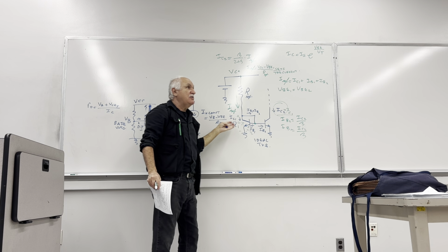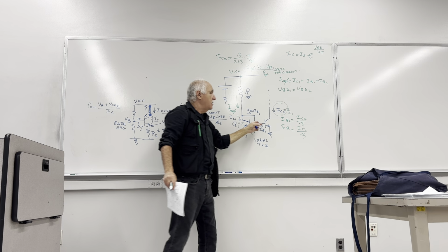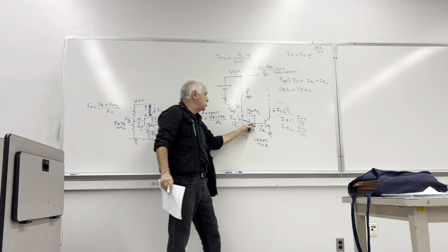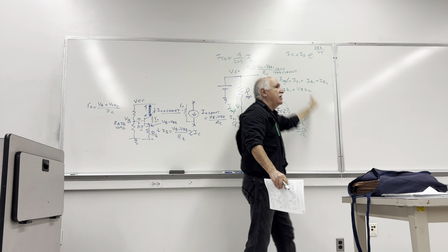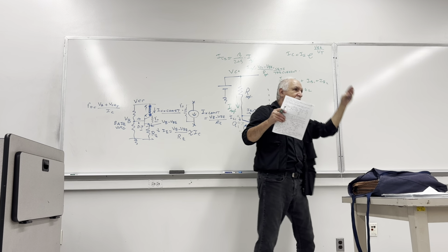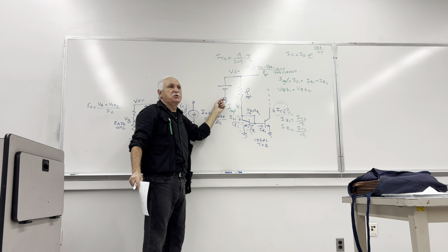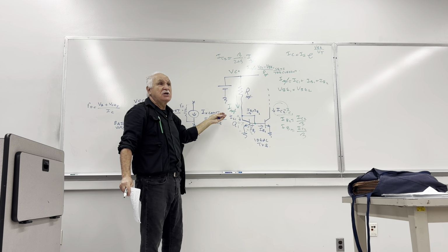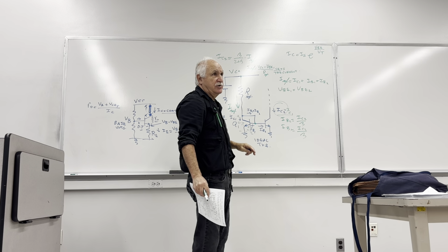Now the nice thing about this arrangement, gentlemen, is we can copy. Put transistors here, third one, fourth one, fifth one, connect all the bases to one place, and all the rest will generate their own currents. So they can simultaneously bias other stages from one common source. And that is significant. So mirror imaging is a popular type.